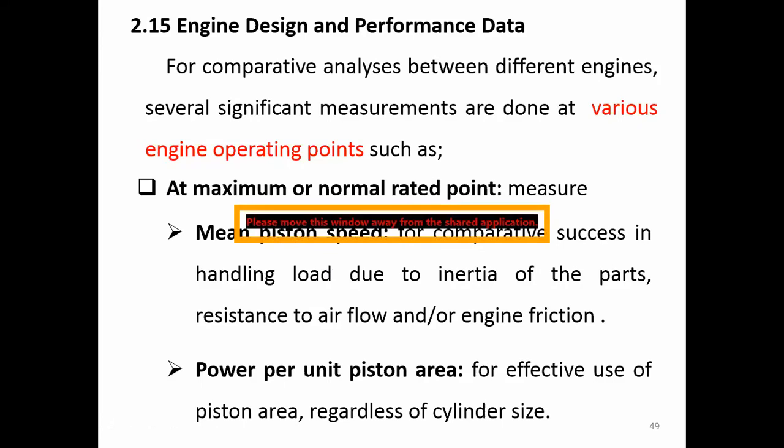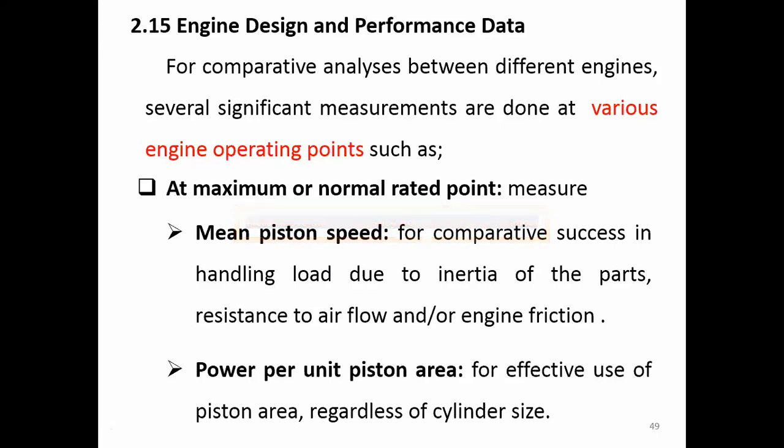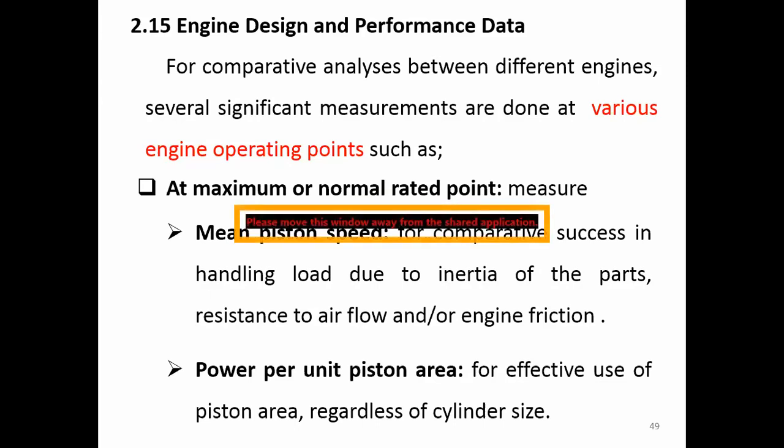Why? We want to compare the success of each engine in handling the load that is due to the inertia of the part, right? Because piston moving is considered to be the inertia. So we want to look at when the engine runs at maximum or normal rated condition, what is the mean piston speed that it can keep? Because this will indicate how well it can handle the load that happens because of the inertia of the part.